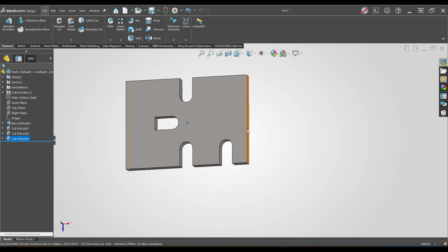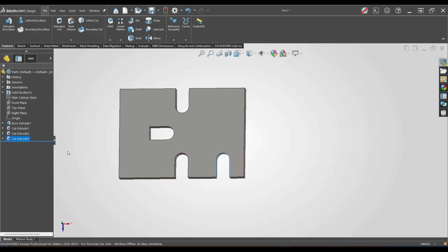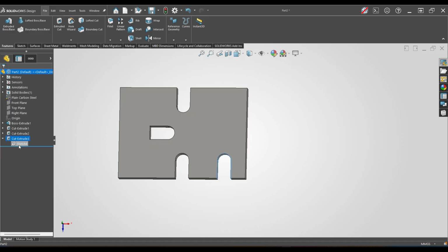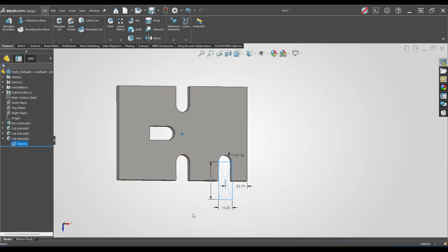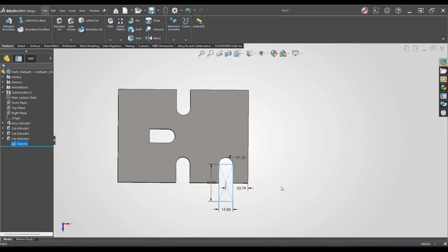Just know that if you understand the select contours piece to your features, extruded base, extrude cut, and some other things, you will have a lot of options, and you don't have to waste a lot of time trimming stuff out. And then what'll happen is, if I click on the sketch, then I see exactly everything. Let's say you have a complex sketch and you want to refer to that. Well, if I trimmed everything out, I wouldn't have been able to see exactly what was on the sketch in the assignment or lesson. So that's that.